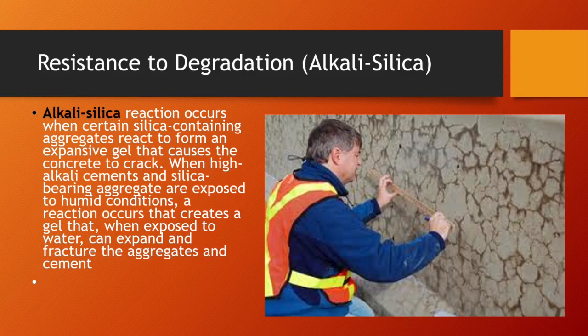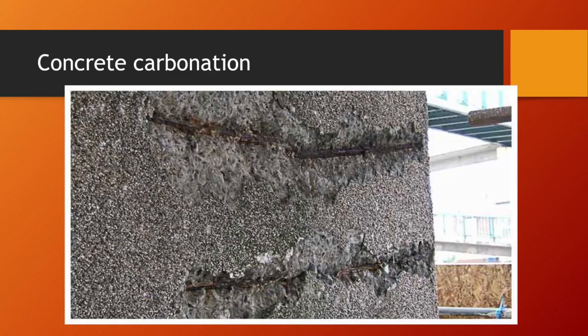So when high alkali cements and silica bearing aggregate are exposed to humid conditions, a reaction occurs that creates the gel. And then when that's exposed to water, it can expand and fracture the aggregates and cement, just like the freeze thaw. Okay, but it's the same. You can see there, it's the same outcome. It's the delamination or dilapidation of the concrete itself. It's starting to break down.